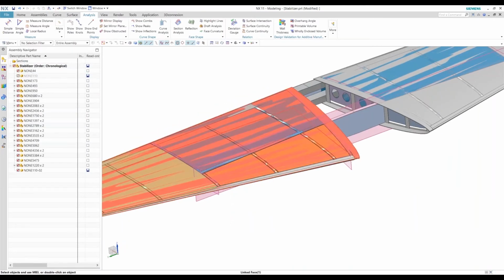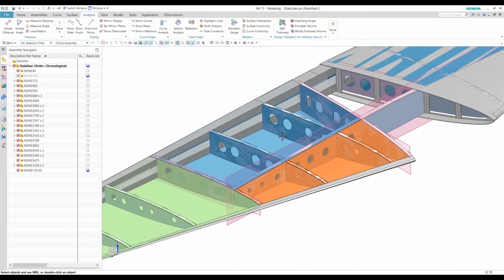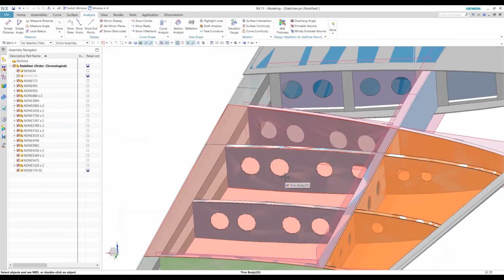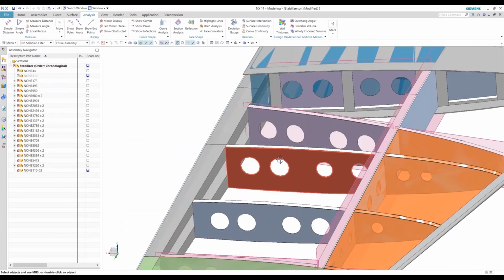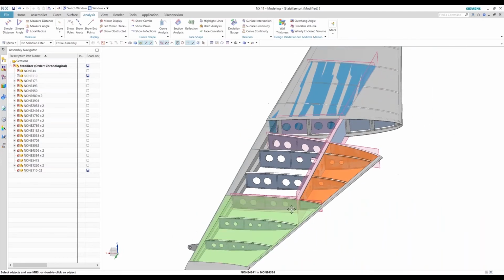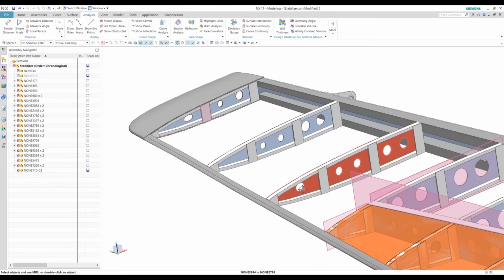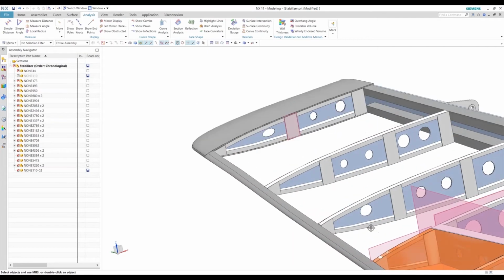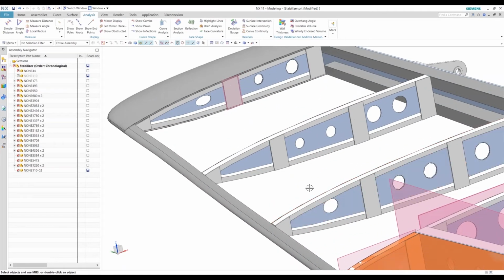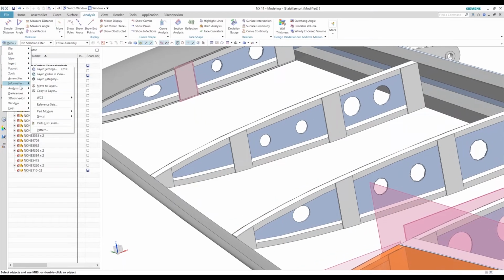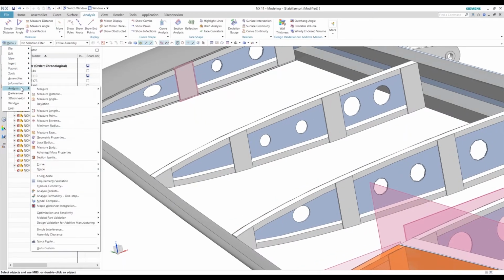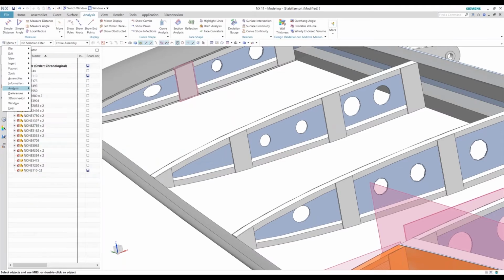So in order to find that area, we can go here, and it's easy when it's just a circle, but if you have something like an oval or something complex here, you can take the area of a curve. So if you go to, let's see, analysis, advanced mass property, area using curves,